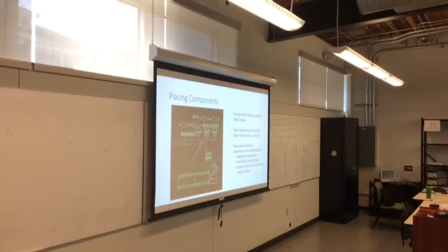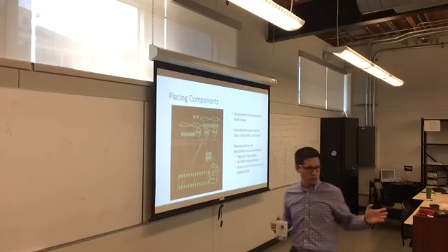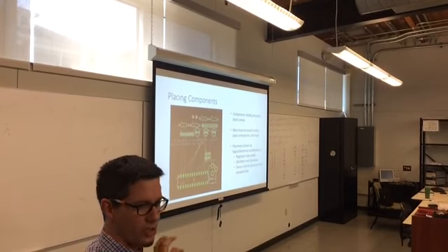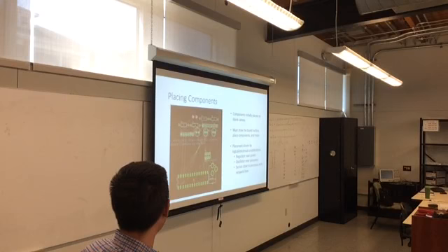The advice I can give is that if you look at a well-made board, its layout is logical. So the power supply is near where power comes in. The processor is near its clock. All of the analog pins run in a row out to one another. If you look at, you can't see the layers in this one. But if you look at a board, all the pins are going to kind of flow in parallel. You're going to have logical routing to your power and ground. My advice is to place the components where they should be physically and then kind of make the routing work.